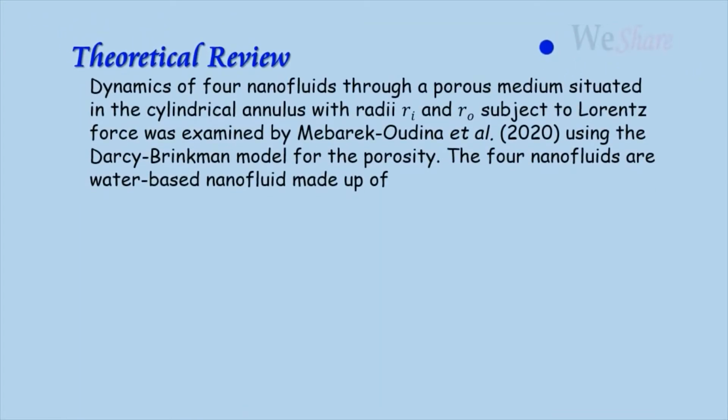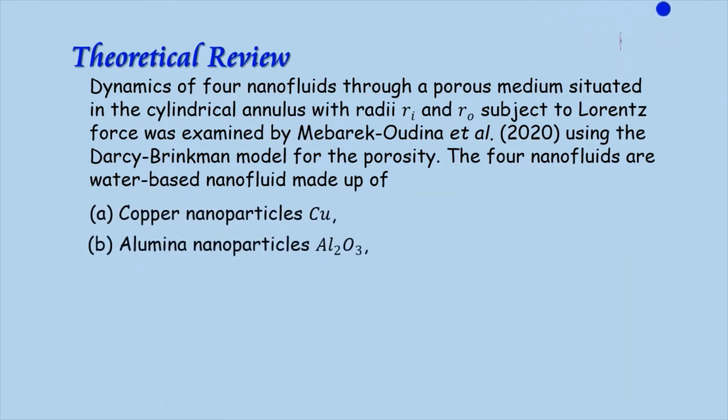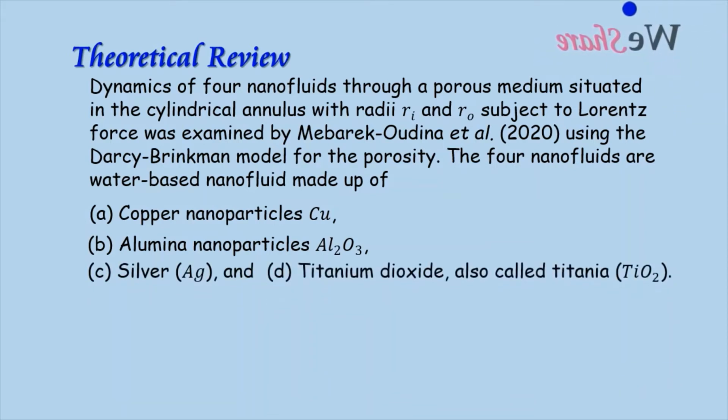Dynamics of 4 nanofluids through a porous medium situated in the cylindrical annulus with radii subject to Lorentz force was examined using the Darcy-Brinkman model for the porosity. The 4 nanofluids are water-based nanofluid made up of A. Copper nanoparticles, B. Alumina nanoparticles, C. Silver, and D. Titanium dioxide, also called titania.